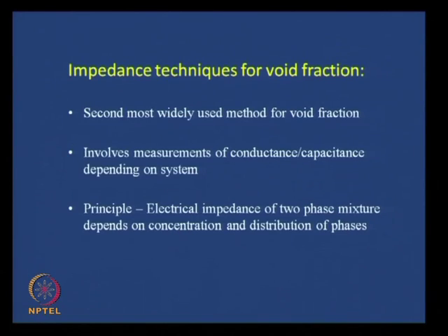If we are operating at a higher frequency, then capacitance is dominating. In that case, the method works on the difference in the dielectric constants of the two phases. And if we are operating at lower frequency, then it is based on the difference in electrical conductivity of the two phases. Usually for an air water system we prefer conductivity probes, but for certain other systems it is better that we depend on the dielectric constant difference.